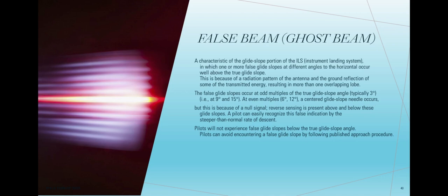A pilot can easily recognize this false indication by the steeper than normal rate of descent. Pilots will not experience false glide slopes below the true glide slope angle. Pilots can avoid encountering a false glide slope by following the published approach procedure.